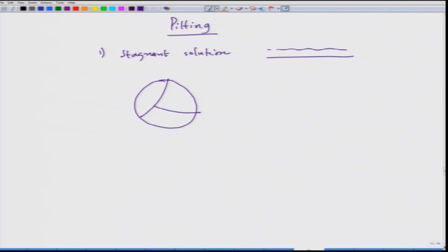These grain boundaries can be seen because they are attacked more in the etchant, since the grain boundary is a very active region. So, if we compare the reduction potential of grain boundary and grain body, the grain body has a positive reduction potential as compared to the grain boundary. That is why the grain boundary region acts as an anode. So, it dissolves more.